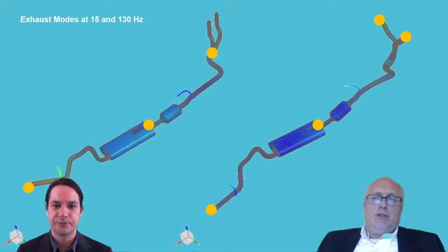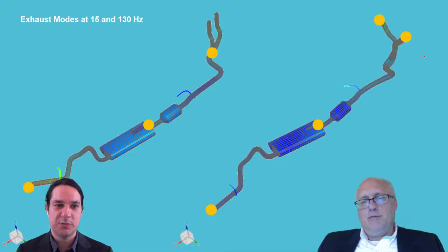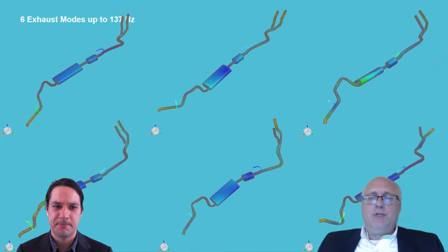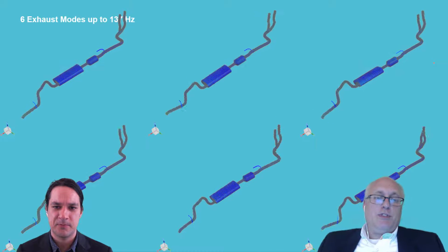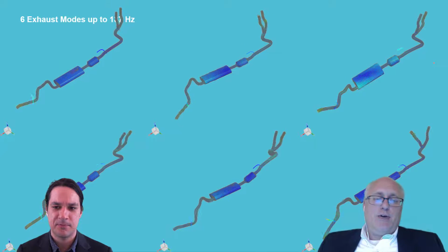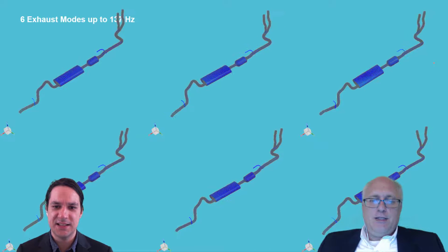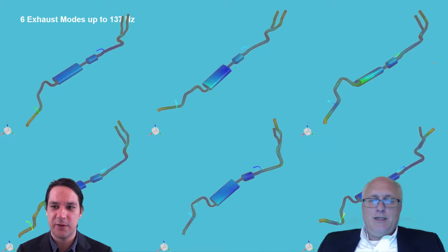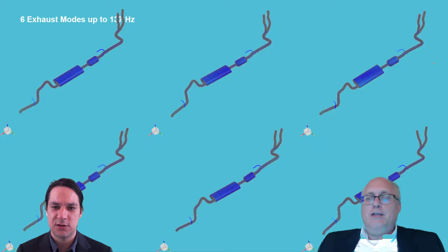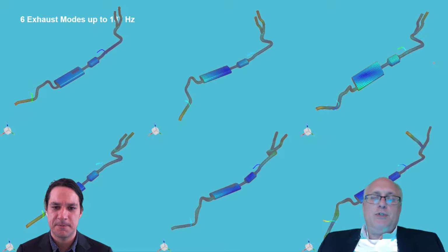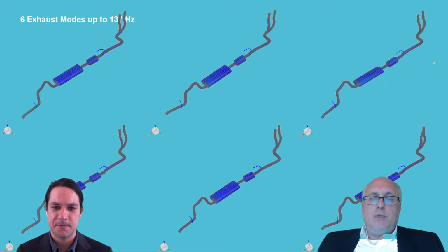So how many modes does an exhaust normally have, Nick? Probably more than 2. I can say that with confidence. Yeah, it depends on the frequency we go up to, but if we're interested in sound of the exhaust, for example, how high in frequency can humans hear? Well, I guess ideally up to 20 kilohertz, although functionally, I'm not sure I can hear that high in frequency. Yeah, but that's several modes. I'm only showing 6 here, and you can see it'd be pretty hard to determine what modes we need.